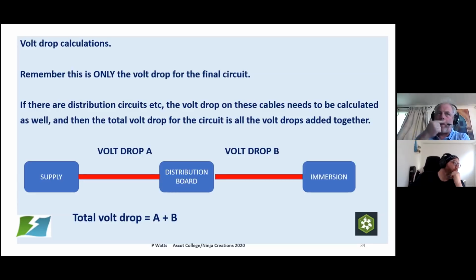Daniel said, how would the 1.2 multiplier be appropriate or accurate if they are being tested at lower ambient temperatures? So if we're thinking about the 1.2 multiplier and we're testing at lower temperatures, so the multiplier isn't actually in effect. The 1.2 multiplier is effectively down to the current running through the cable. So when you look at guidance note 3, it says when you're doing the volt drop calculations, only for volt drop calculation, you use that 1.2 because you're looking at a circuit under use. And it says apply it to the values in table B1. So you've got to apply it to those 20-degree values.